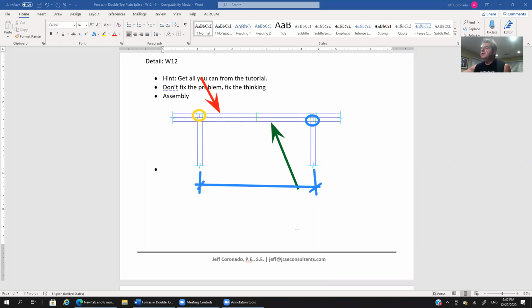After all, if we're looking at a 2x4 stud wall, these 2x4s that are laid horizontally to create the top plate can't be 40 feet long, if that's how long your wall is, right? It can't be 30 feet, it can't be 20 feet, it can't be 60 feet. The contractor is going to have to splice these, put these butt into each other to create as long as the wall is. So there have to be splices.